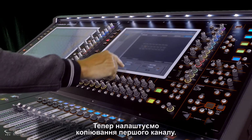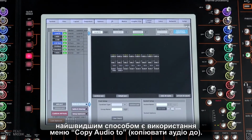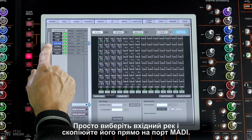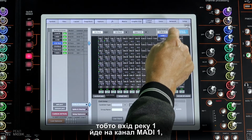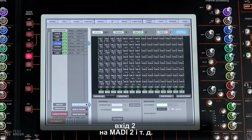Now let's set up the first audio copy. If you're copying whole racks of inputs to your recorder, the quickest way is to use the Copy Audio 2 menu. Just select the input rack and copy it straight to a MADI port. This sets up a one-to-one patch, rack input 1 going to MADI channel 1, input 2 to MADI 2, etc.